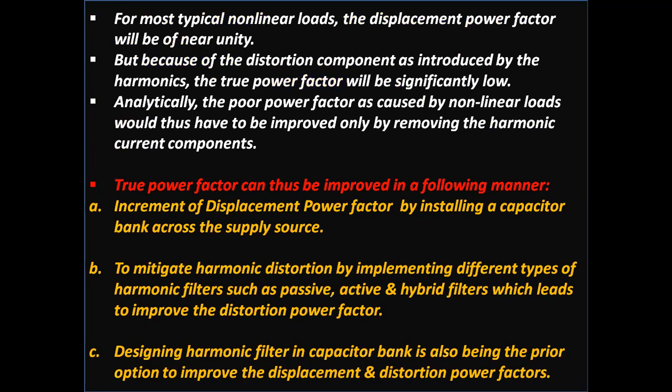For most typical nonlinear loads, the displacement power factor will be near unity, but because of the distortion component introduced by the harmonics, the true power factor will be significantly low.